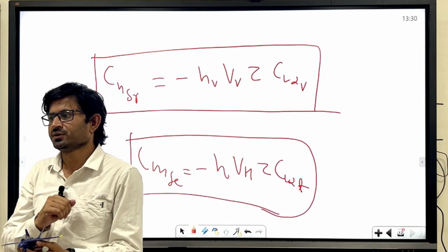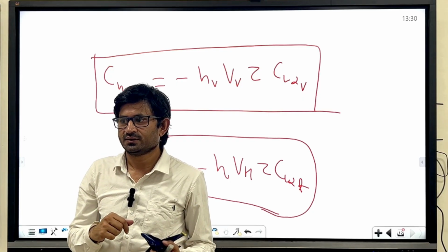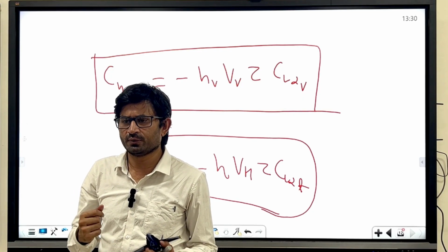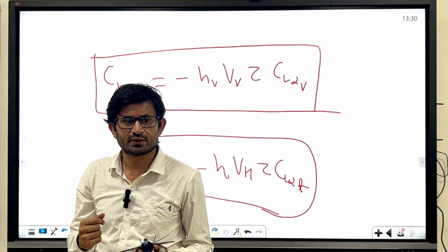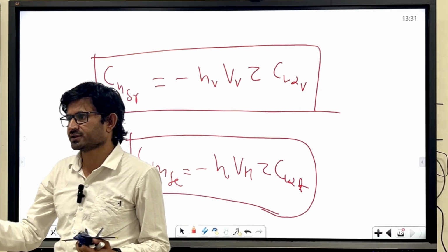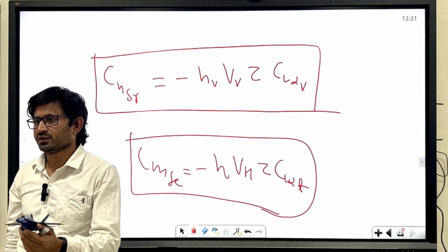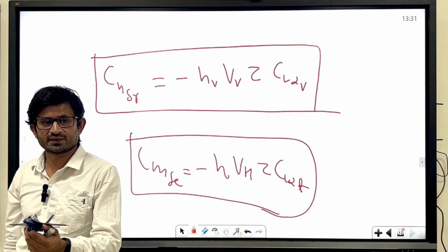Okay. So there are many cases where the rudder is very important, and one more important case, for example, is a situation where the crosswind is coming and you want to land the aircraft. In that case, you can handle the side slip angle.